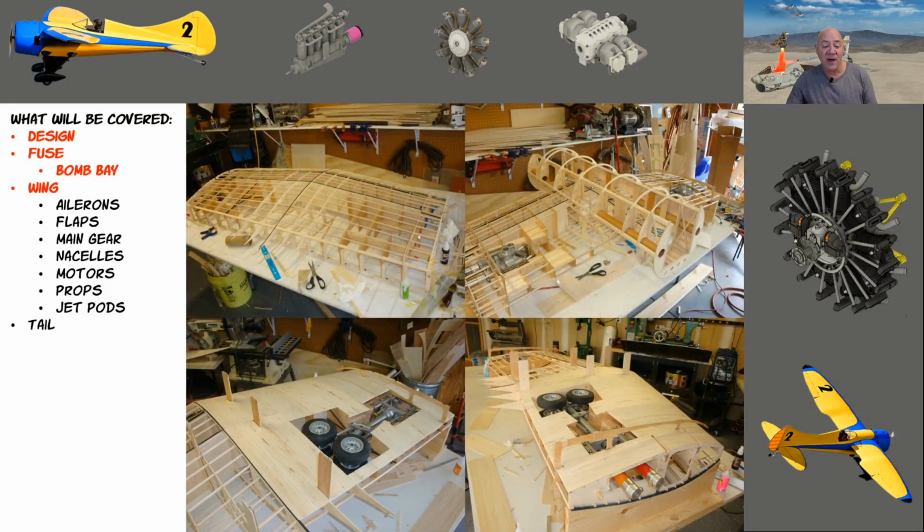So when you think about one of the hardest things when you design an airplane is actually getting landing gear to fit in the wing without removing too much of the strength of the wing. I've seen RC drawings of like B-29s where they cut into the spar and build like a box where the landing gear goes. That is a horrible idea. You want to try to get continuous spars to run tip to tip, and you want to be able to strategically put your landing gear either right behind that spar or in front of a spar. You never want to run a spar into a landing gear and then build a box around it and go on, because that box over time will get fatigued, made out of plywood.